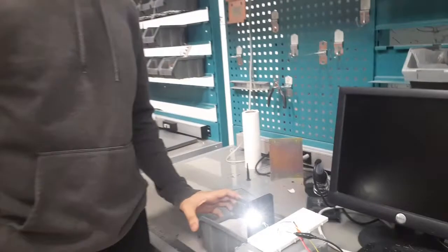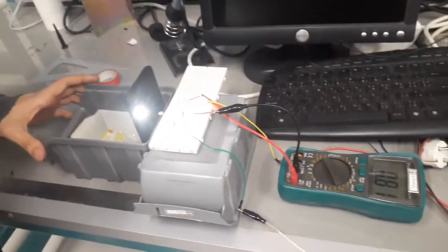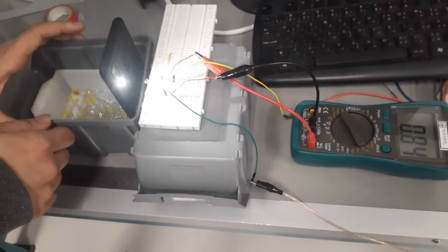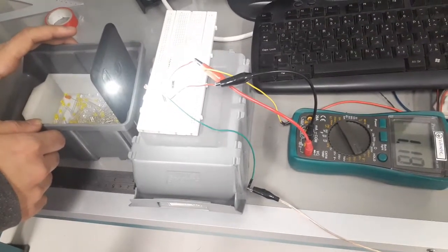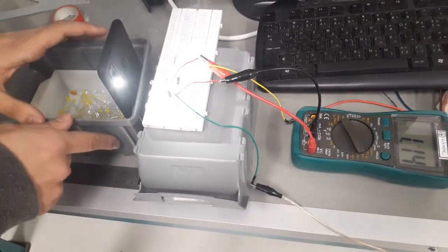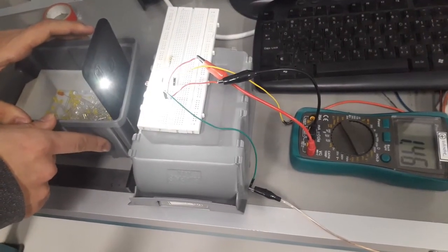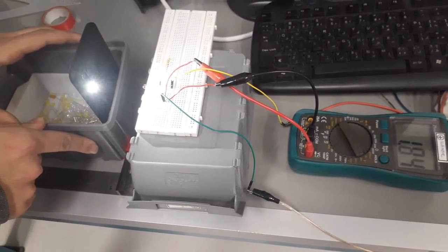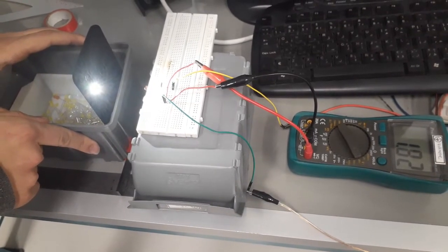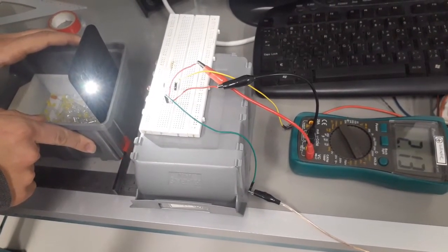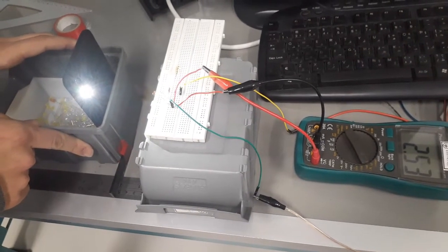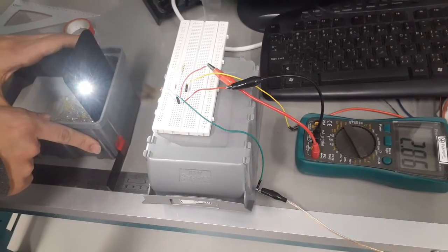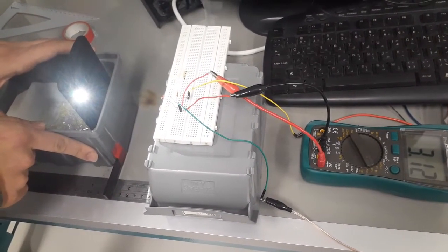Now we are going to collect our data using our configuration. When the ruler shows the 0 centimeter value, the distance between the LDR and the flashlight is actually 2 centimeters. So we start to take our data from 2 centimeters, and we are going up to 25 centimeters. We are going to increase our distance by 1 centimeter for each measurement, and we are going to collect our voltmeter data, or voltage data, during this process.